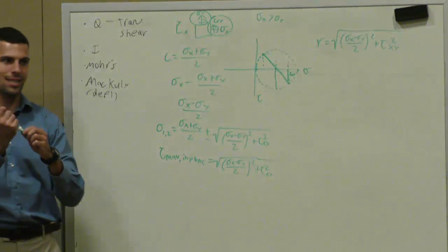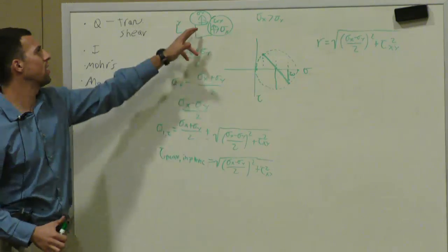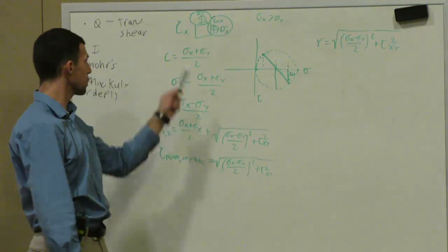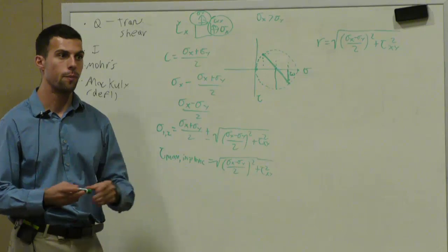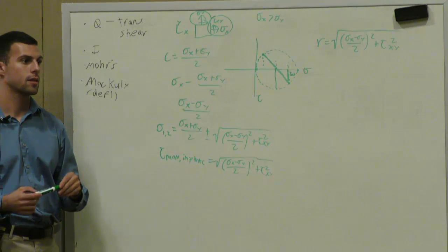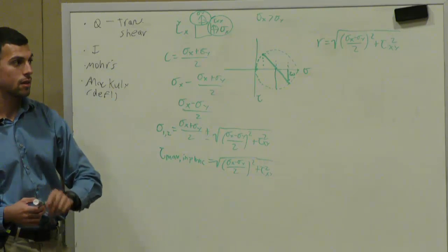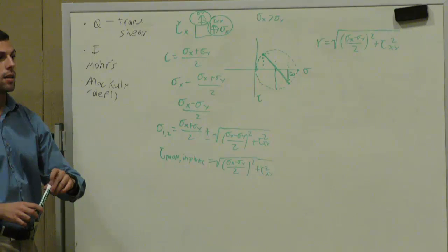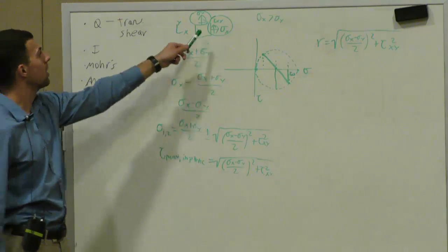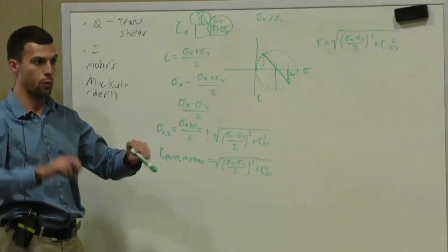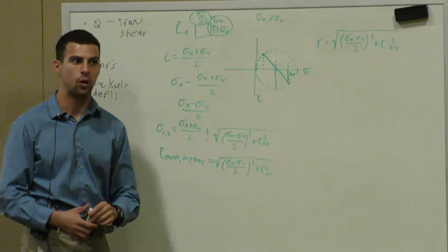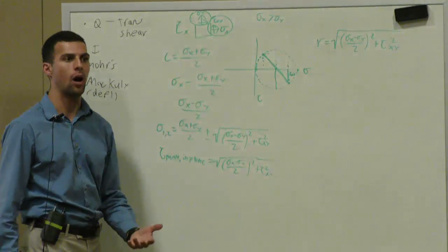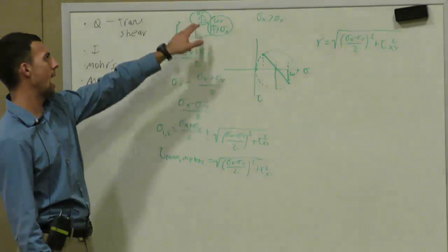Graphically, it all relates. So now do we understand, given a single stress element, so let's go back through that process a little bit. Not your max and mins just yet. We establish the coordinates. We take each side as a coordinate, and so we graph this normal stress and the shear stress that is associated with it, and let's do the same on the other side.